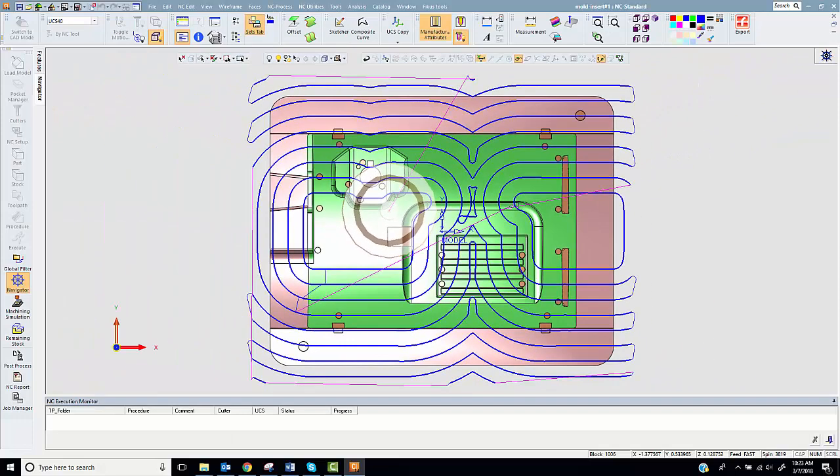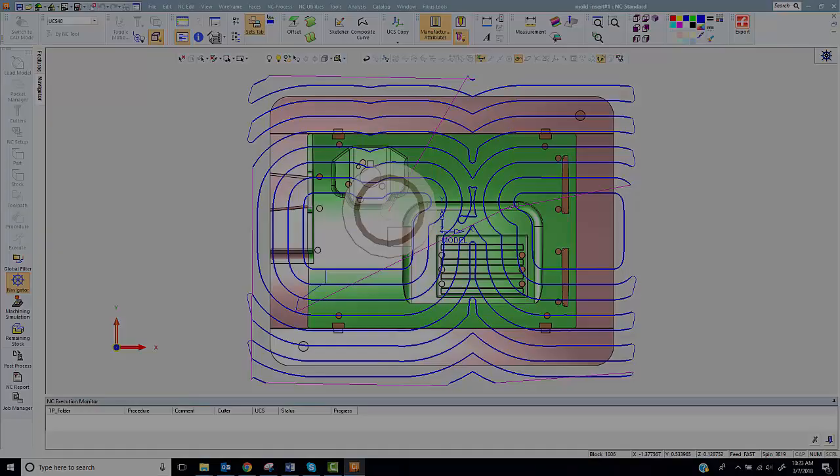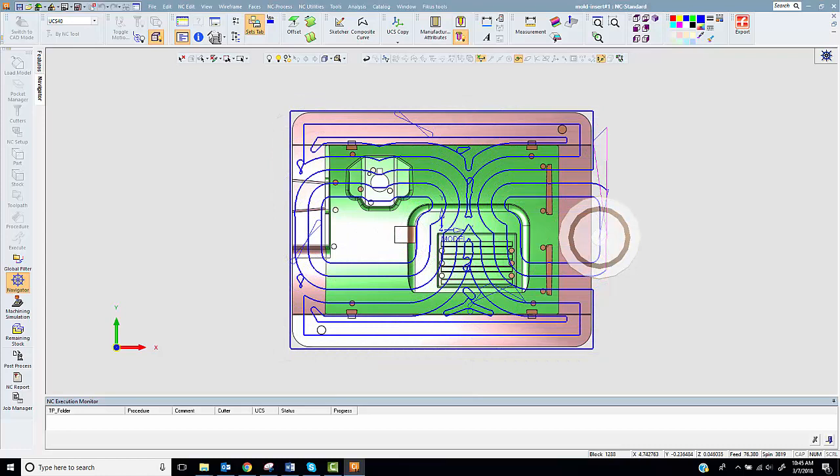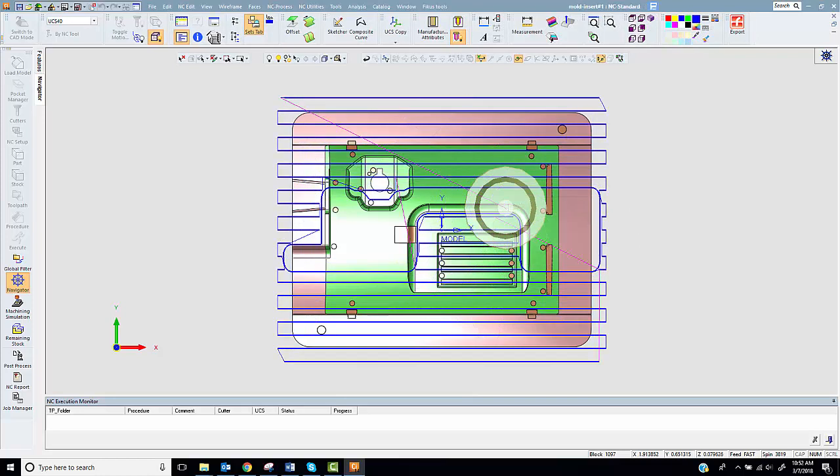As you can see, this machining pattern is bidirectional. It does the final pass against the part as a climb milling motion. The user can also define climb milling only, shown here with the system optimized strategy of stock spiral. The user has the ability to define basic spiral strategy as outside in or inside out with stock offset passes against the part. And as the last option in this video, the user may choose a parallel strategy, bidirectional or unidirectional, with the climb final pass against the part.